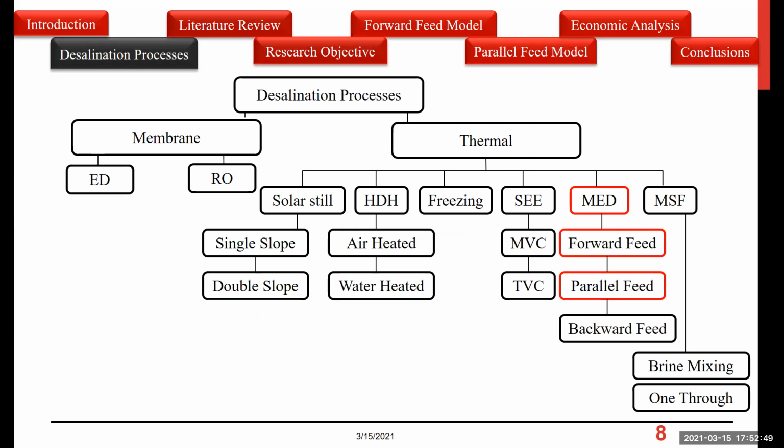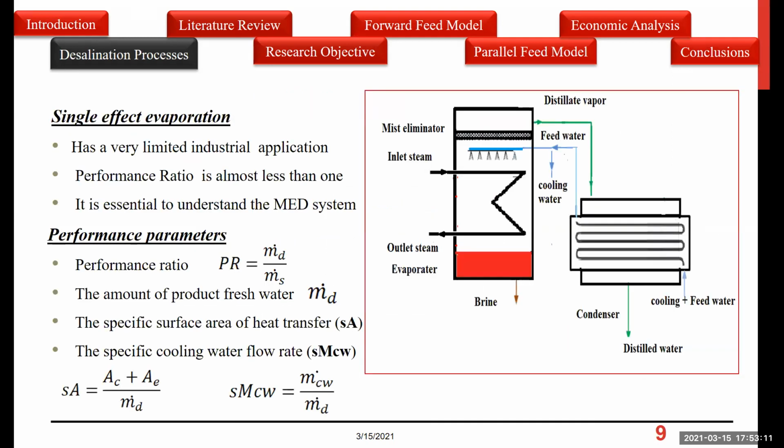Or the classification can be done based on membrane-based or thermal-based, and you find that there are many branches for the thermal-based desalination. Actually, we can say that we have covered many of them so far, except for the last one that we have not yet talked about, which is the MSF, multi-stage flash desalination system. This is a single effect operation system, and that's something that we have been working with and have analyzed already.